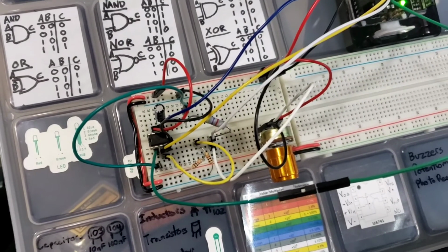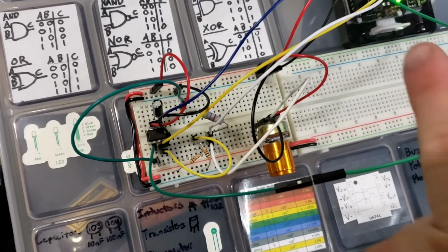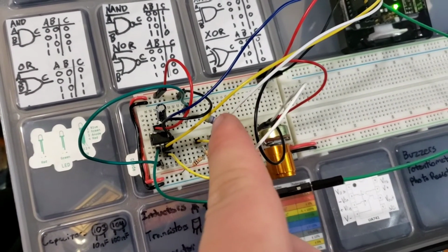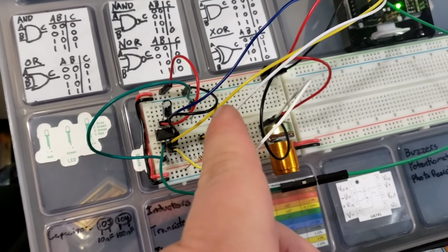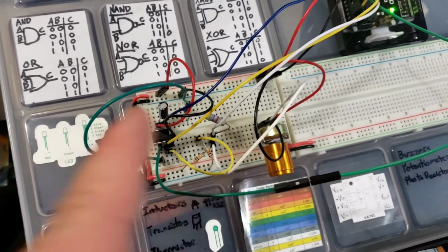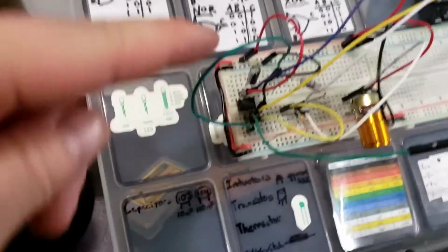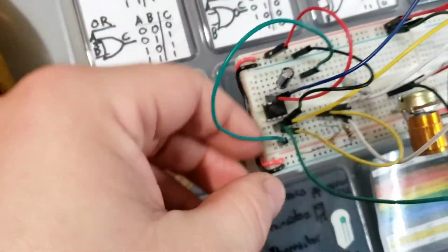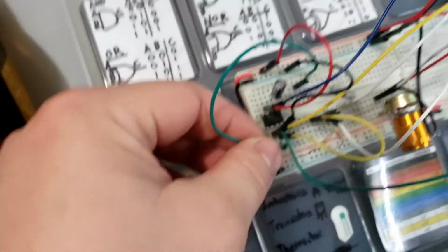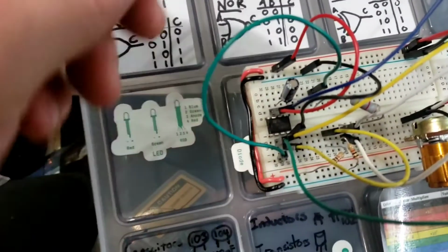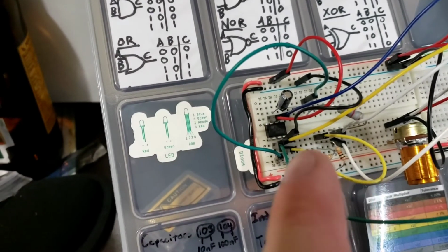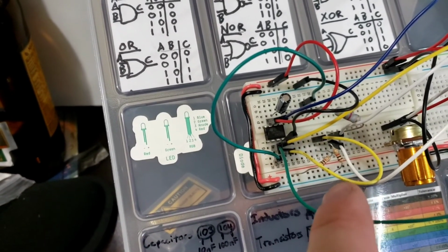Over here we have our circuit for exercise 4. We have our power coming in through our potentiometer, and then going through our 4.7 kilo ohm resistor, which then comes from this green line to our V positive terminal, V negative terminal into our op amp. We have our capacitor, and then we have our voltage divider for our 2.5 volt bias.